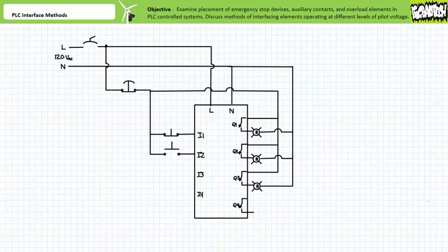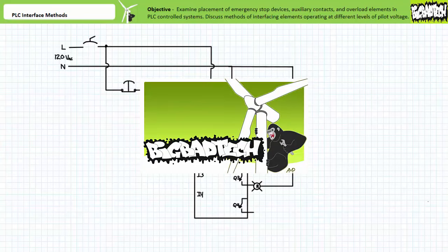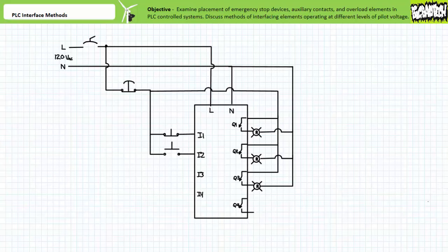Recall systems using traditional hardwire relay-based ladder logic simultaneously represent both interconnection and function using techniques as discussed in the ladder logic documentation lecture. However, since a PLC's principal advantage is its reprogrammable nature, one really only needs to schematically represent the hardwired connections. Very often, a PLC-controlled system represents this schematically as field inputs simply disappearing into the PLC and outputs selectively energizing or de-energizing the field outputs. However, this gives no indication as to what opens or closes these outputs.